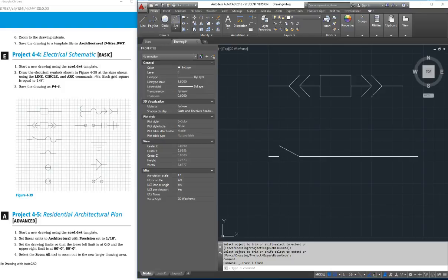That's going to be right here. I'm going to come up to my arc. I'm going to do start end radius. So I'm going to do a start, 1, 2 grid squares, end. Oh, and look at that. I did it the wrong way again. That's okay. That happens all the time. So escape, because you can see it arcs up then down.